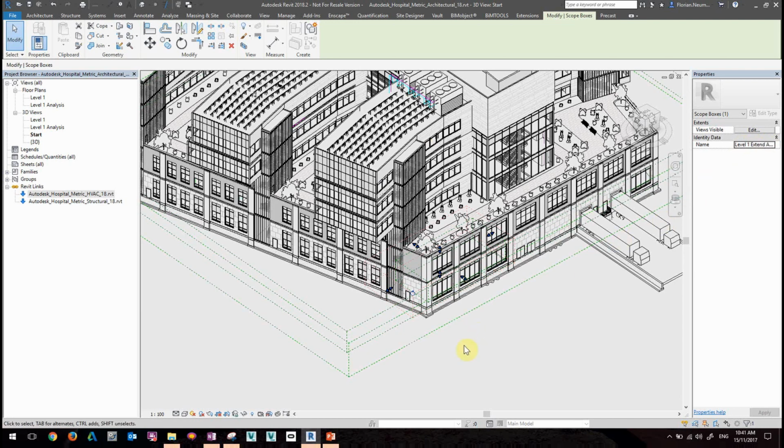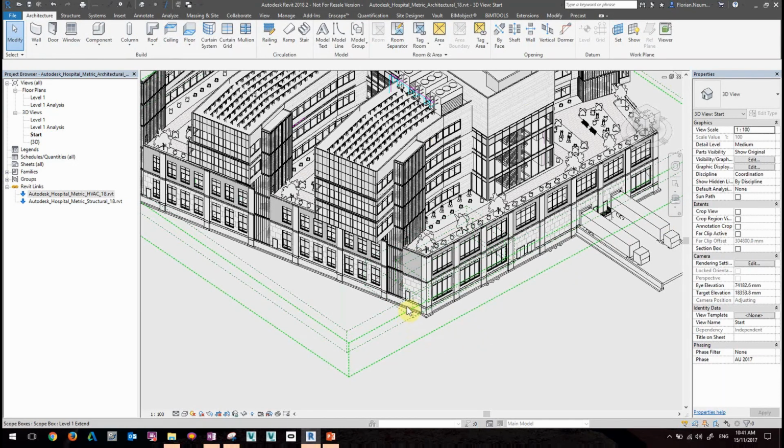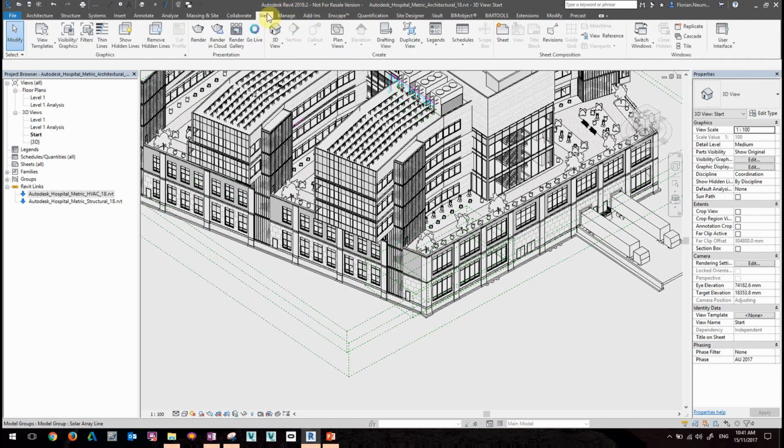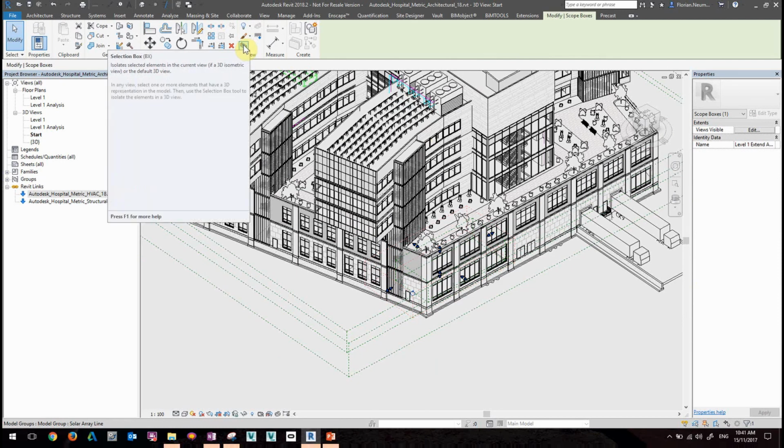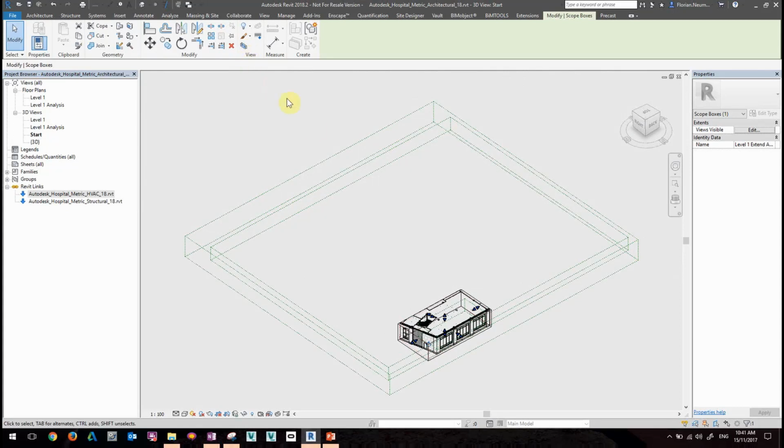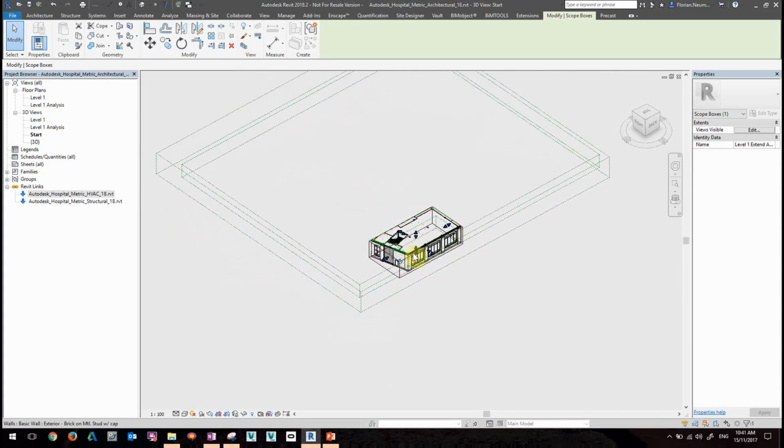That's ready for my analysis, so that I can immediately browse and jump to this. Revit offers us a pretty cool tool if we want to communicate the areas of interest with scope boxes. First, under the view, we can set up scope boxes in a plan view. In a 3D view, it doesn't work. If I select my scope box, I can immediately create a section box around it. BX would be the shortcut here, and then we are immediately in our area.